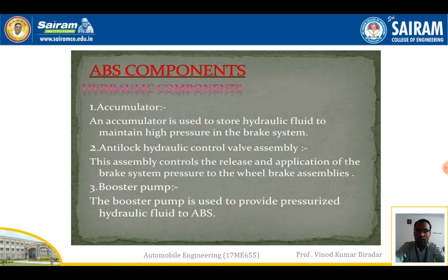Second is the anti-lock hydraulic control valve. By using this valve, the assembly controls the release and application of the brake system pressure to the wheel braking system. It will release the pressure from the accumulator valve, or that is the master cylinder. Next is the pump, called the booster pump. The booster pump is used to provide pressurized hydraulic fluid to the anti-lock braking system when required.